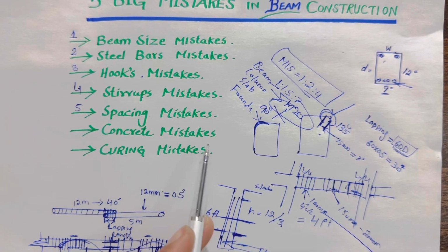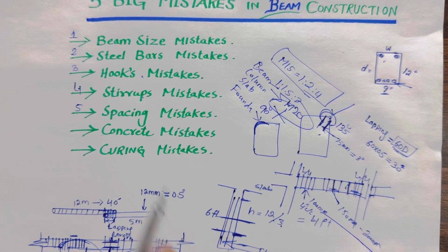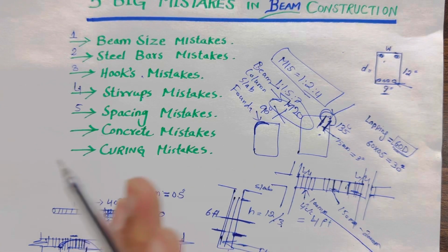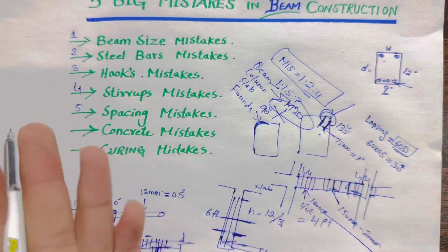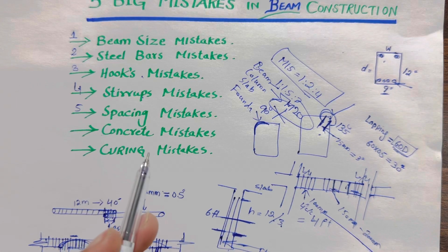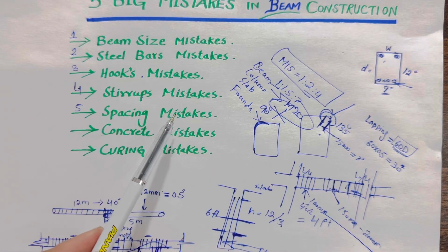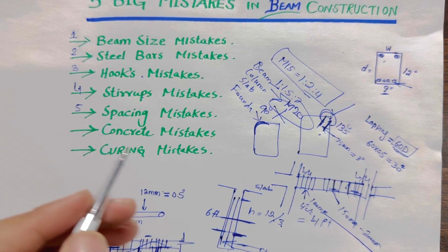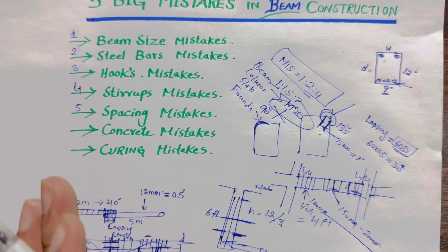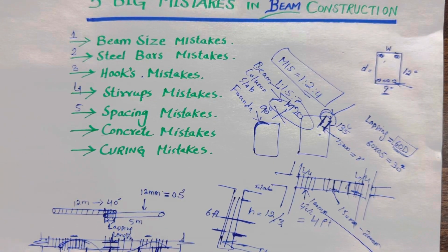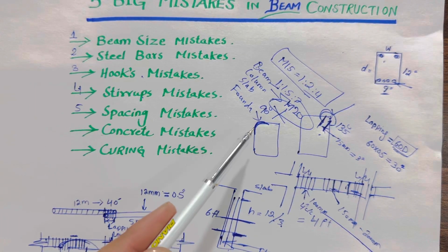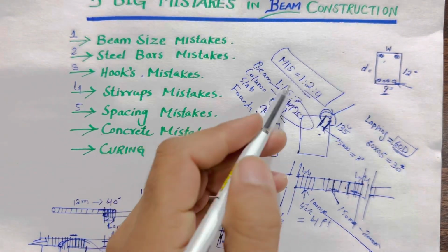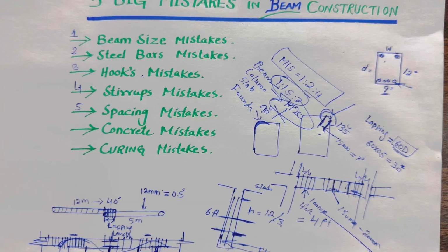So this is a very important grade of concrete, because steel can't give you full strength on its own. When we combine the steel with concrete, inside the concrete we are providing the steel, which is called reinforcement. Therefore concrete is a very strong member, especially in construction material. So the concrete ratio should be provided according to the structure load, but it should not be less than M15 for a normal residential building. But for a commercial building, it should not be less than M20.